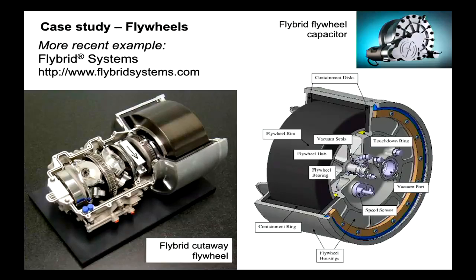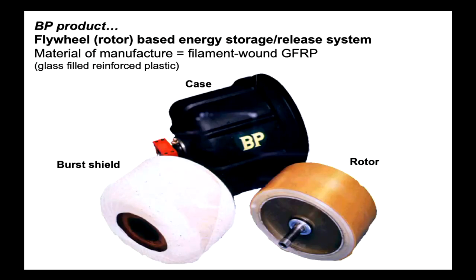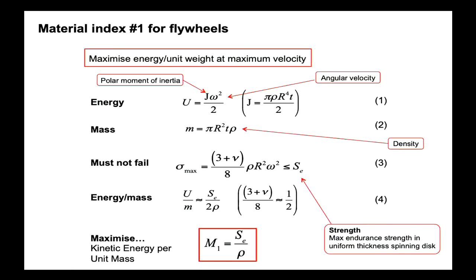And I'll go back 2 slides. Rotational stored energy becomes translational or radial kinetic energy. Thus, this burst shield, if there is a risk of fracture and failure, is expected to prevent that radial motion of bits from travelling beyond that shield itself. Okay. So we create our equations, and I've highlighted everything that's going on there.